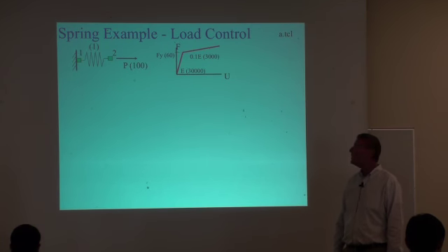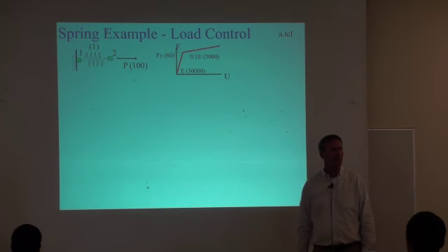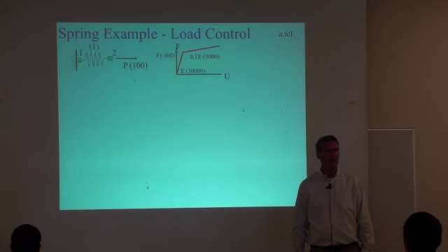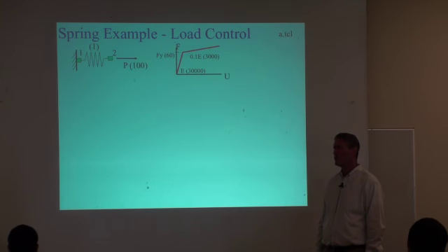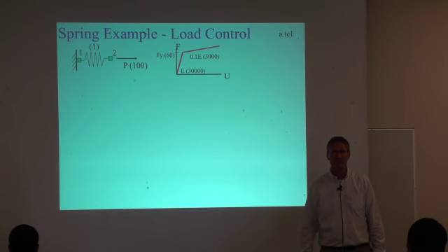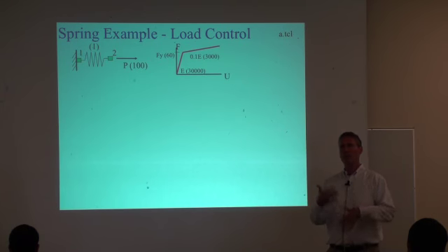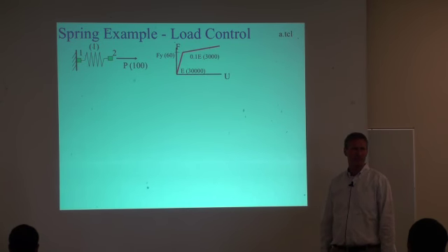Basically it's elastic with a Young's modulus of 30,000 up until a yield point of 60. After that, it's going to go at 0.1 times E. So after yield, it'll be straight hardening at 3,000. So this is the simplest nonlinear example I could think of. Now I'm going to show you the Tcl commands to generate this model.